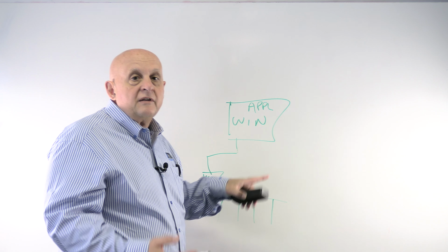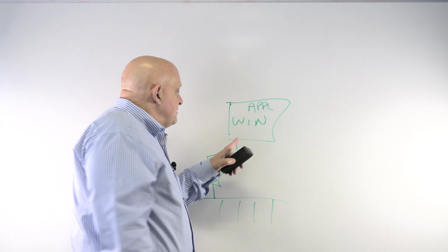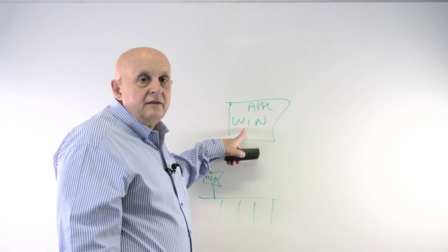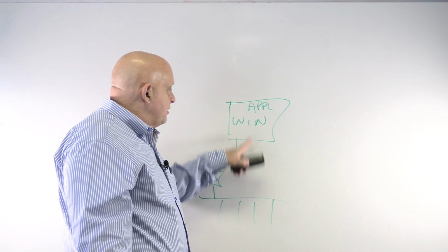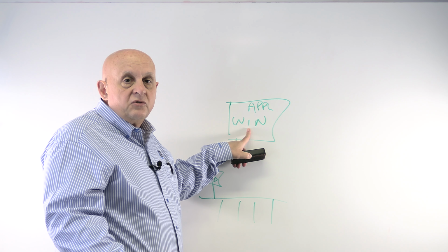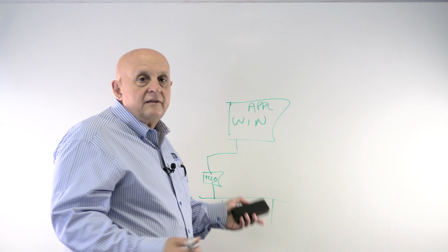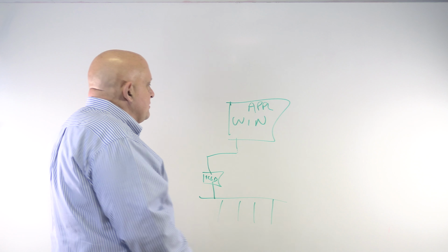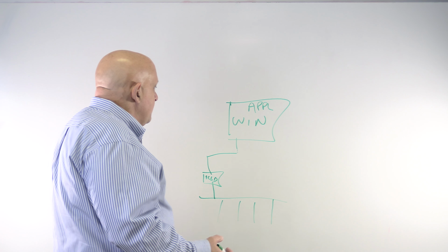The downside of that, of course, and I admit that, is that IT tends to come and update these things whenever it feels like. Even if it's 2 in the morning, if you're running production, they might upgrade this Windows PC and reboot it and take your control system down. So there's a plus side and a minus side to doing this.